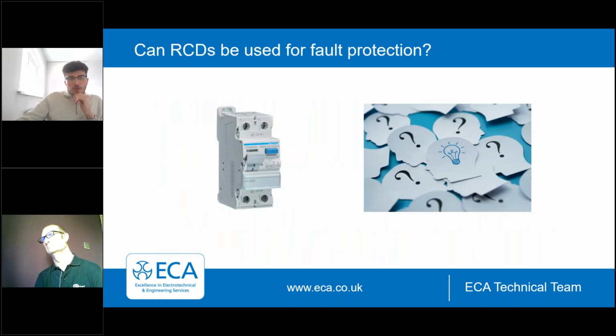Okay, so last few bits now really. Obviously throughout the presentation, we've been focusing on earth fault loop impedance. We've been focusing on the basis of automatic disconnection using an overcurrent protective device, a fuse or a circuit breaker. Now, something else that we often see, and sometimes get asked, is can we use RCDs for fault protection? And the simple answer for that is yes, you can use RCDs for fault protection.